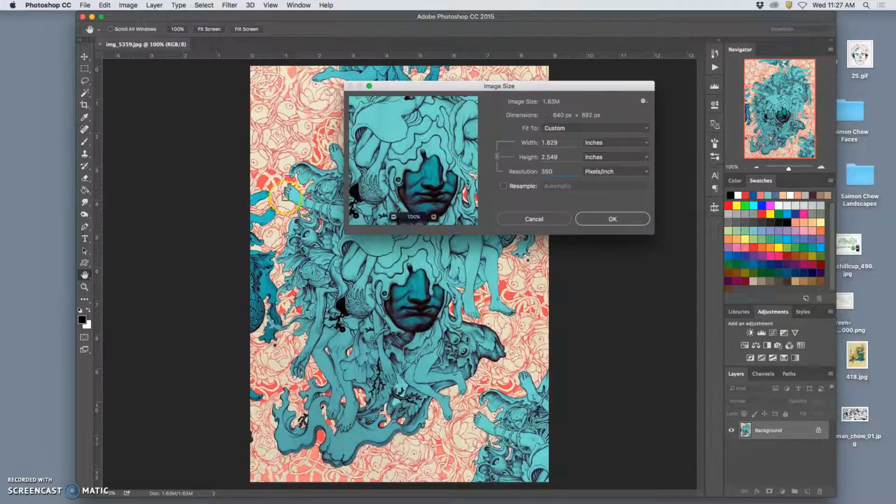So we are going to change the resolution. And the problem with that is it's going to make this image a little blurrier, but it shows you how we can control the size of our pixel grid. And we're going to be building our shapes on top of this, so we want to make it into a file that's the right resolution. So to do that, I click on Resample. And Resample allows me to force it into as many pixels as I want it to be.